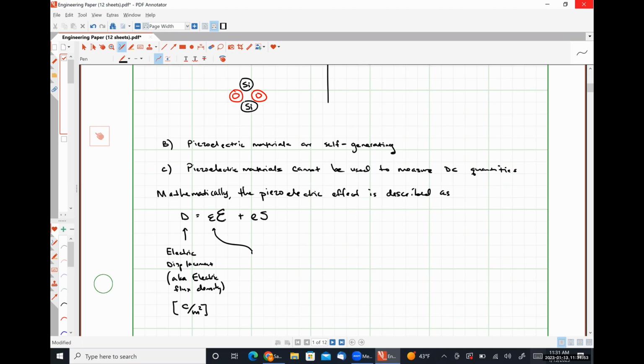Yeah, so we have a little epsilon that looks suspiciously similar to a large script E, but this little epsilon represents the permittivity of the material, which is measured usually in farads per meter or farads per centimeter, farads per micron, farads per unit length. This large script E is the electric field measured in volts per meter typically.